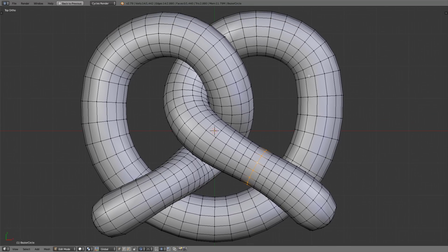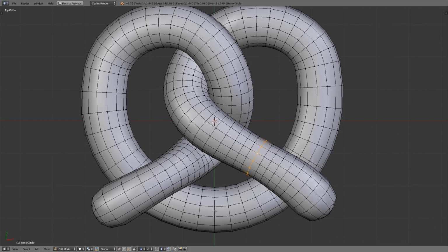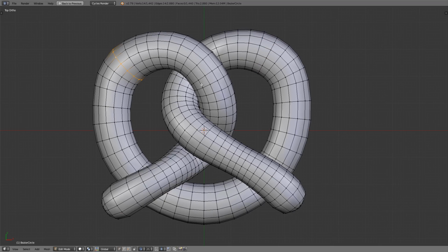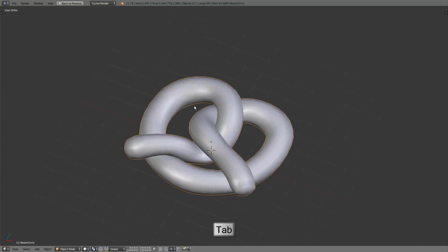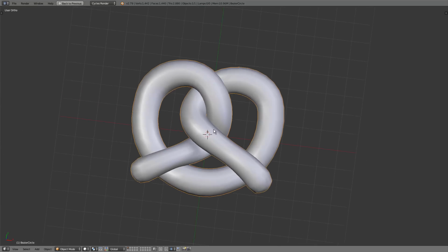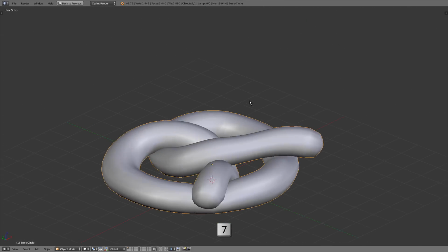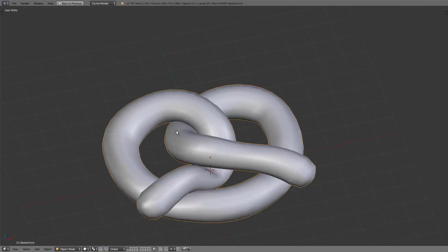Now I'm going to make areas like the top two corners a little bit fatter as well as the bottom. So let me hold Alt and I'll right click on that edge there, then press S and scale it up a bit. And we'll do the same thing for the top corners. So that additional size variation just adds to the realism by being an extra detail so things don't look completely consistent. All right, let's take one quick look around our object, make sure everything looks good before we move on.